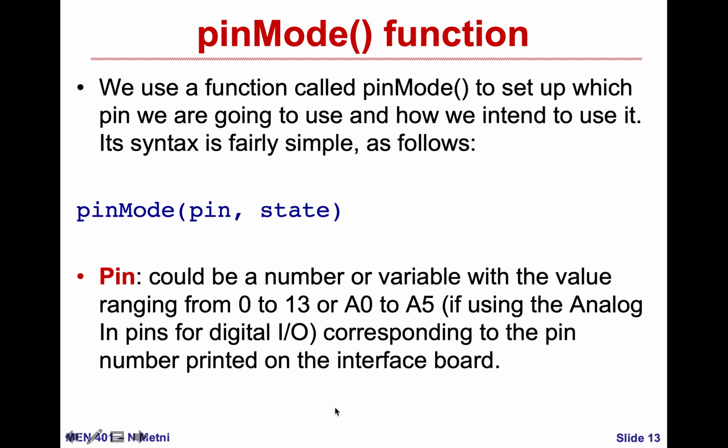So here, let's talk about how I can do this. Here I have 3 main functions that I will explain. The first function is pinMode, which we saw earlier. It's to specify if this specific pin will be used as an input or as an output. The second function is how I can write to an output, and the third function is how I can read from an input.